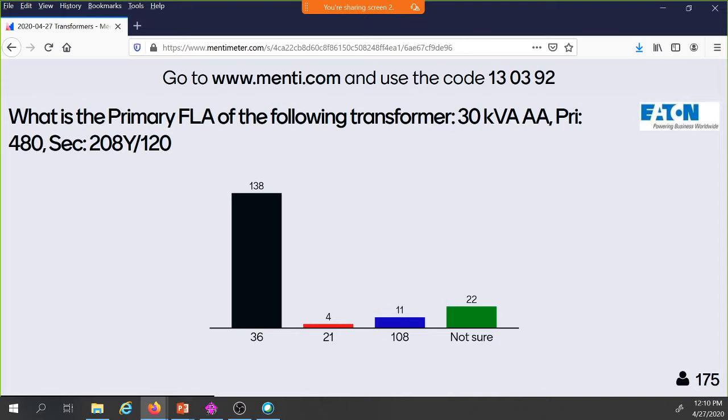I'm going to show you a nameplate to solidify that in your mind. The nameplate for that transformer has both kVAs, both full load amps, all of that information, but only one percent impedance, because you can't change that physical construction. That's why your inrush current's not based upon the fans. It's just the way that puppy's made.